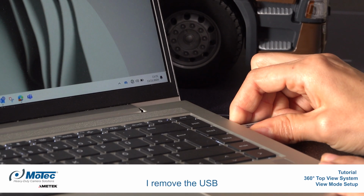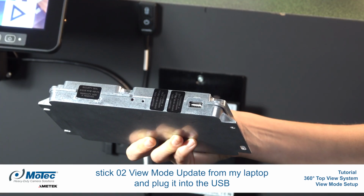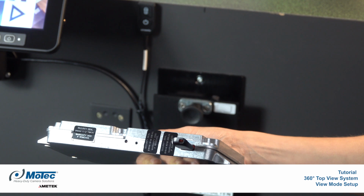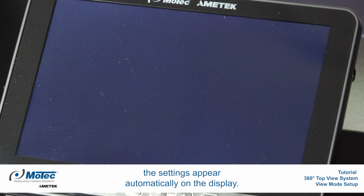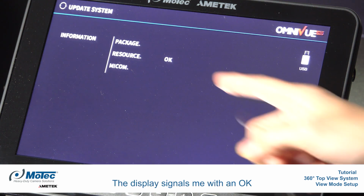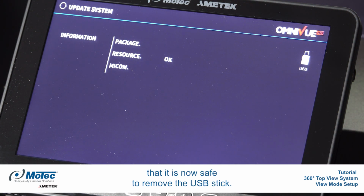I remove the USB stick O2 View Mode Update from my laptop and plug it into the USB port of the video control unit. As soon as I plug the USB stick into the interface, the settings appear automatically on the display. The display signals me with an OK that it is now safe to remove the USB stick.